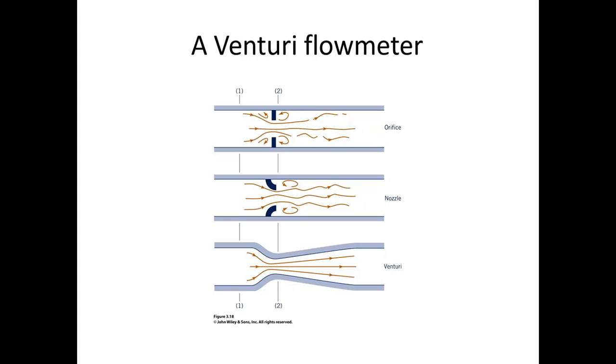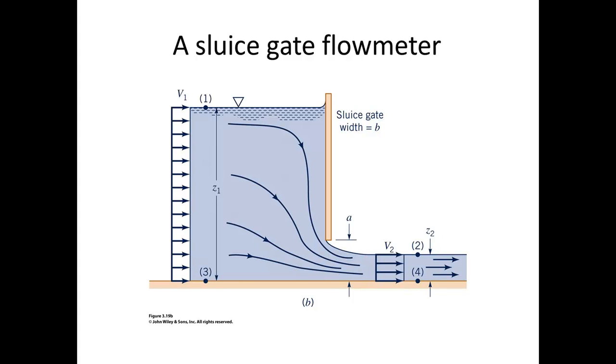With the Venturi meter, you're taking a flow at 1 and speeding it up and measuring it at 2. If you had a large flow, you could bleed off some water and bring it down to a smaller area, like at 2, and take your measurement there. But the measurement is just that you apply Bernoulli at 1 and 2 and you figure it out.